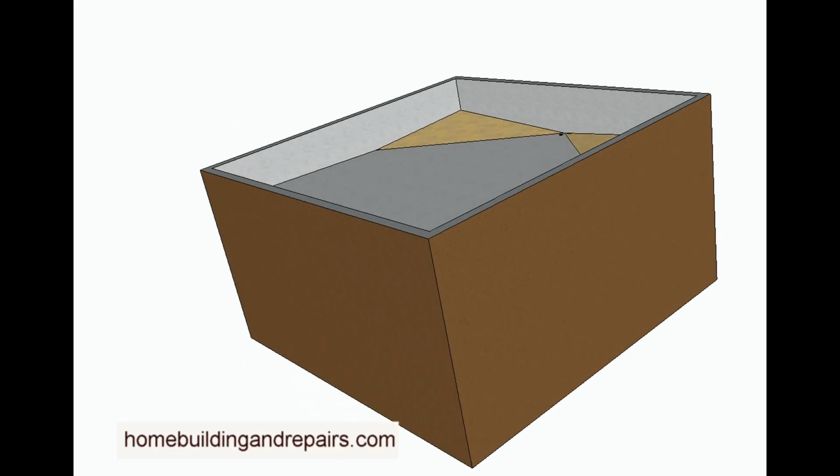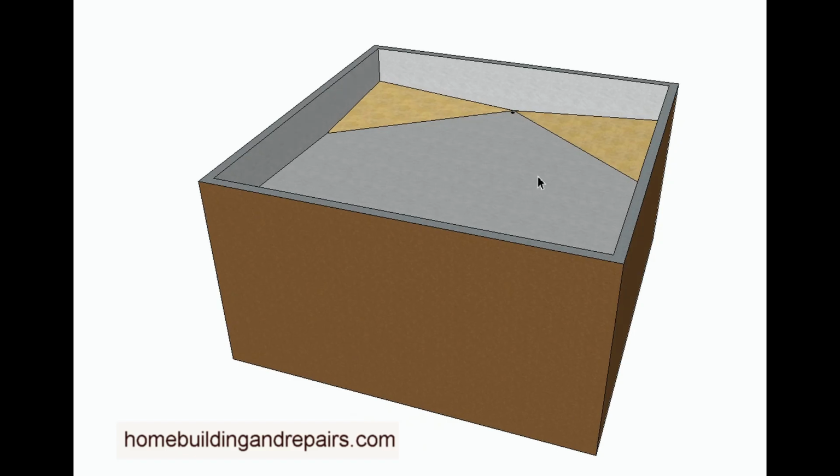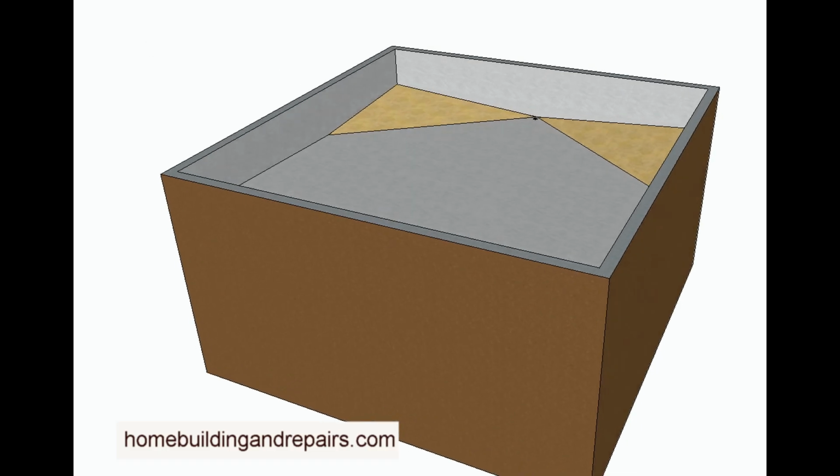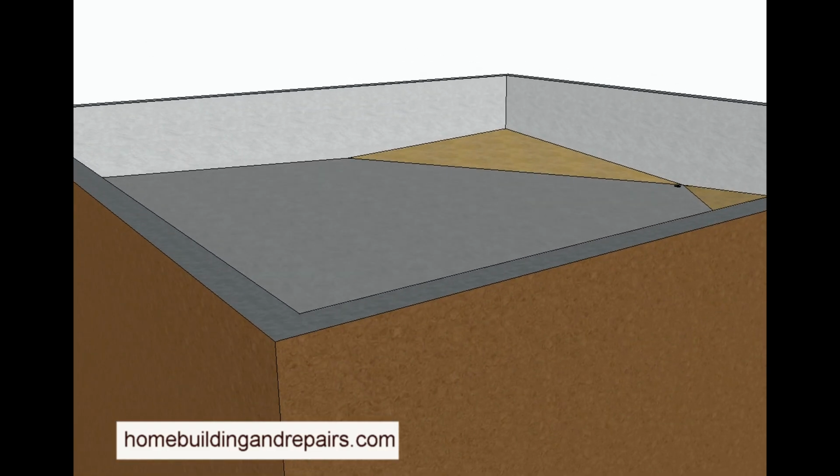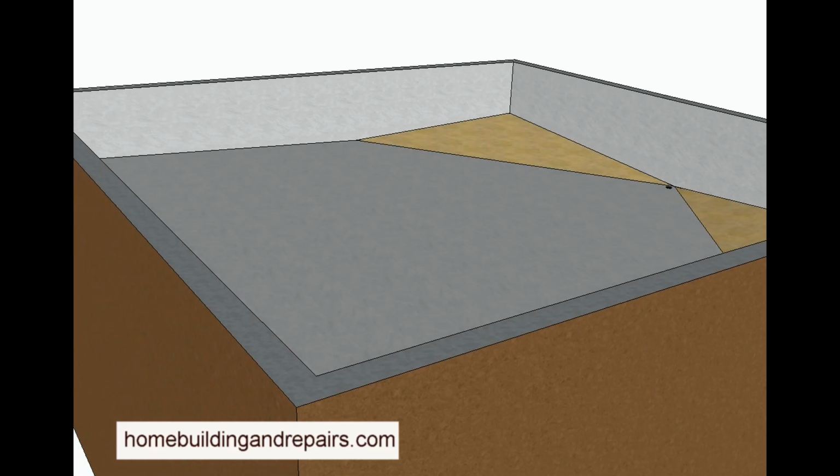Last up on the list would be a low multi-sloping roof system. This is common for commercial buildings or any buildings where you're going to have a wall that might actually extend up past the top of the roof and surround the entire roof, where you would need some type of a drain system. So all the water would slope into the drain, and it would have to be built accordingly to where it can actually slope into a drain and safely off of the roof.